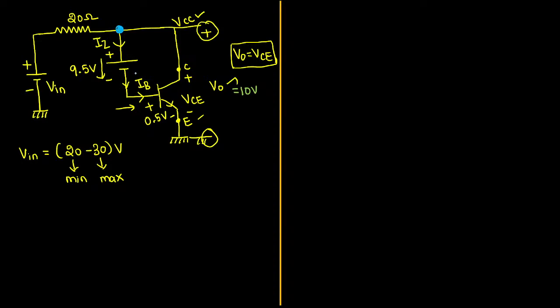To know the voltage at this point, there are two ways. You can observe between this connected to VCC, and this voltage. Let me call it as Vx. Between this, do you have any resistor? No, sir. So if there will be no resistor, then according to normal circuit, this voltage will be reflected here also. So we know VCC, VCE, V0 all are same. Now at this point also we will be having same 10 voltage.